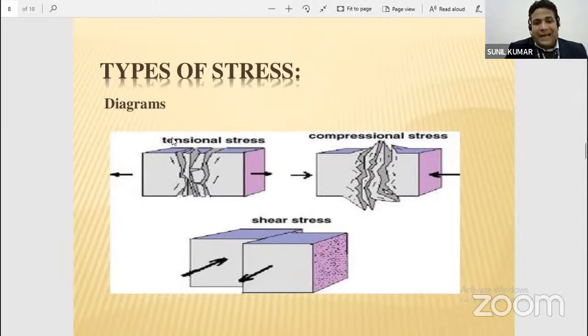So here, if we calculate F minus P, where P is the resistive force and F is the applied force, F minus P is equal to 0 in these regions. So F is equal to P. That is, applied load is equal to resistance force. This is very, very important. So there is no deformation, no change in the shape and size of the bar. If we consider only this section and consider one elemental point with area delta A, a force acts on it, which is known as delta F.